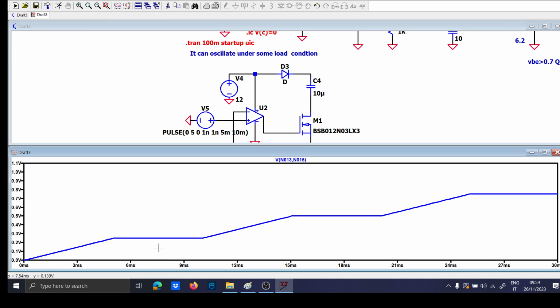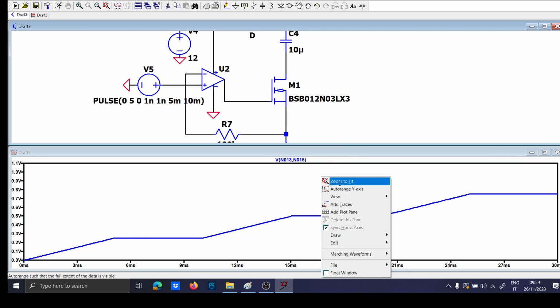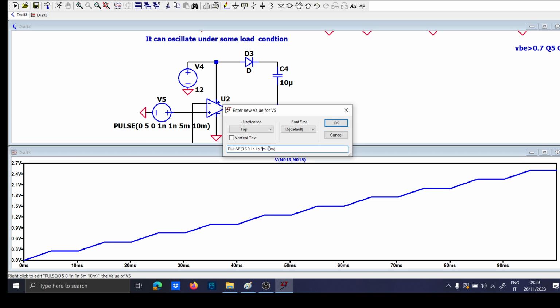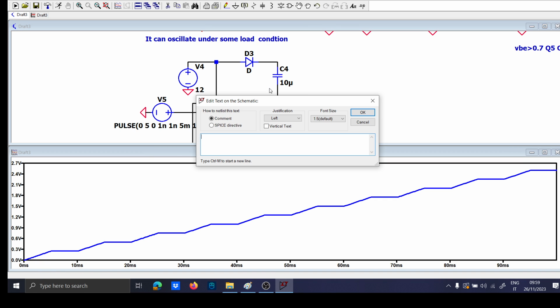The reason why this circuit works, and in the off interval the voltage doesn't go down, is because there is a very high off resistor which basically increases the RC to infinite, and so you have also this way to recharge a capacitor. You can of course increase and decrease the frequency of the pulse. If I increase it and decrease it, I will change the frequency at which I can recharge the capacitor. This is very useful if you want a frequency controlled charged capacitor.